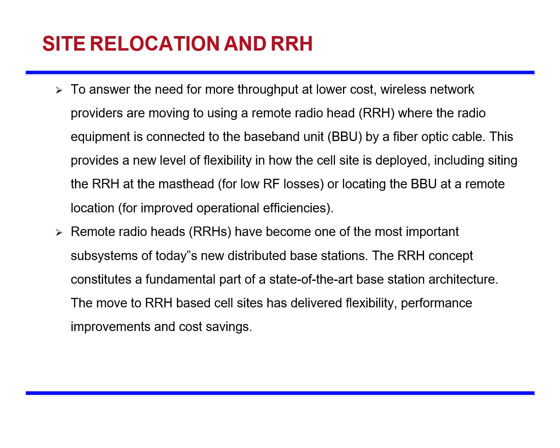Site relocation and RRH. To answer the need for more throughput at lower cost, wireless network providers are moving to using a remote radio head where the radio equipment is connected to the baseband unit by a fiber optic cable. This provides a new level of flexibility in how the cell site is deployed, including siting the RRH at the masthead or locating the BBU at a remote location.